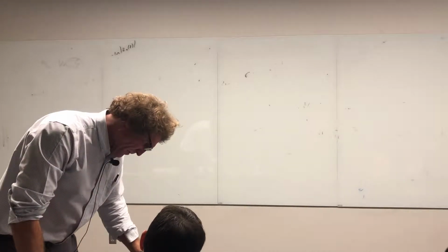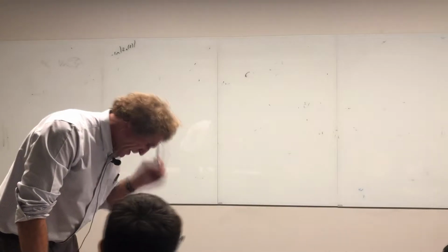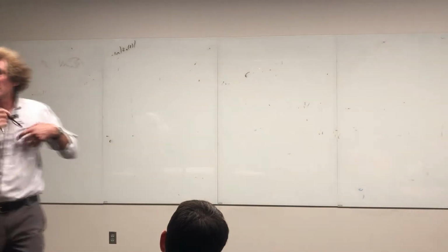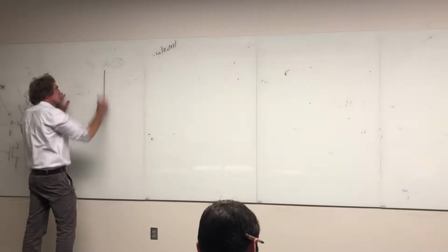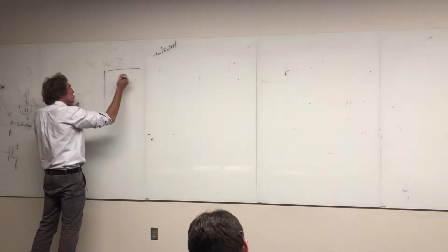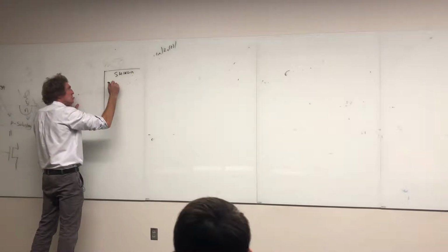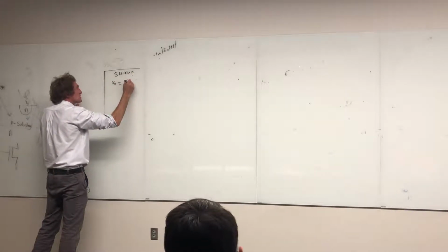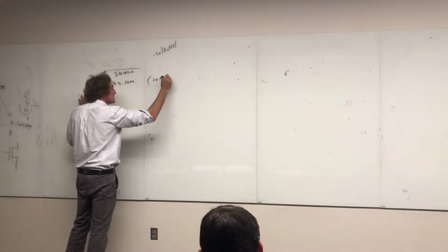Compute the electric field reflection coefficient for an air-steel interface. All right. We can do it, but it only comes down to one thing: knowing what the frequency is and knowing what mu relative is. This is for 1045 steel. So here's the whole idea with the shield. This is going to be the shield here, and it has a mu relative of 1,000. Now, I think I put that down. This is 1045 steel.